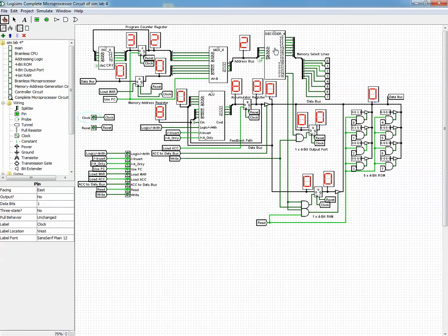So first of all we need the decoder to hold the value that activates this register, which is the value of 15, because the 15 is connected to what enables this register, which is value F. So I'll put here F because this is the only controlled thing that I have. So here is F, and I'll try to pass this F to this decoder so that it activates this line and activates this memory register.